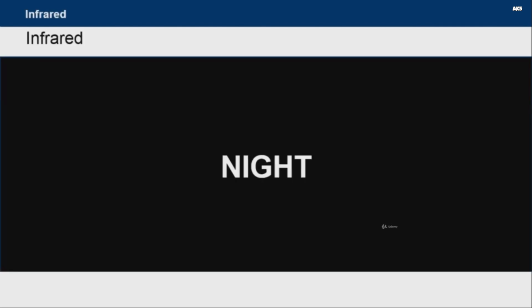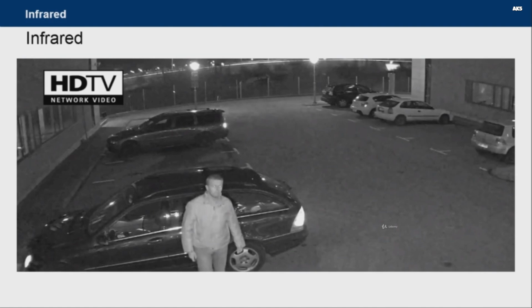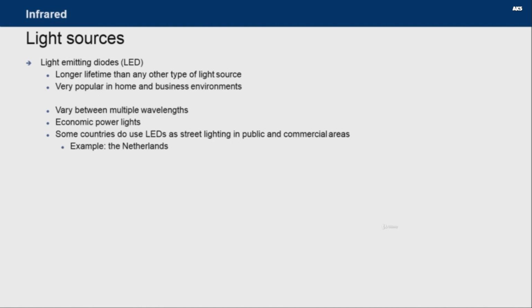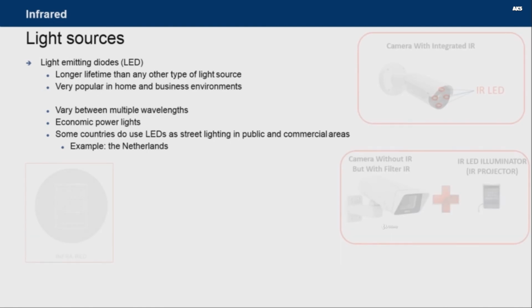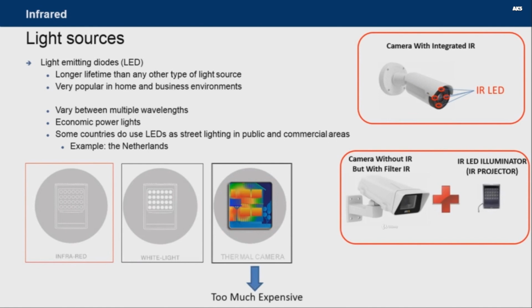Most crimes happen during night or in dark environments, but with good illumination in combination with a security camera, it's easier to recognize details during criminal activities. To capture a good quality image in low light or dark conditions, a day and night camera that takes advantage of near-infrared light is required. For detection in complete darkness and difficult conditions such as smoke, haze, and dust, you can use infrared light, white light, or a thermal network camera, which provides the best solution but is still more expensive than the visible camera.